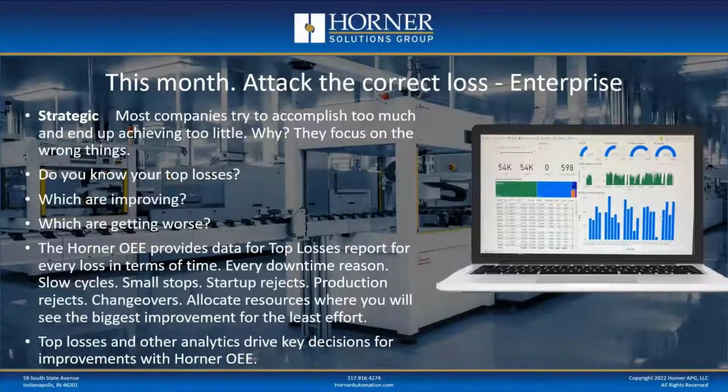Some of this goes to cloud-based dashboards, and some of it may be just within the plant type dashboards. It's all up to the IT department today to determine how they're going to show that visualization. This is basically going to look at all of the parameters, the A, the P, the Q, and the total OEE. Then it shows actual production information and quantities of parts made, as well as how they produce throughout the shift. That's what these types of dashboards are good for. And usually these are for multi-plant applications or multi-zone applications where they want to see different zones that have a lot of work cells in each zone.